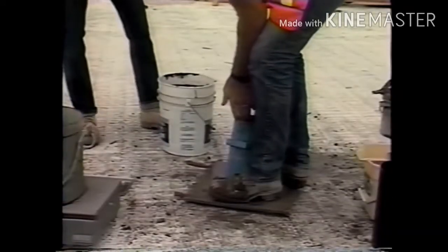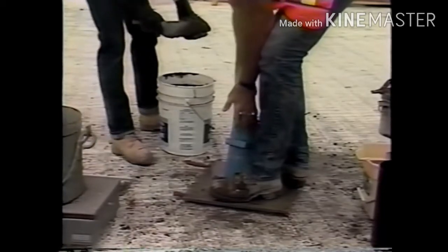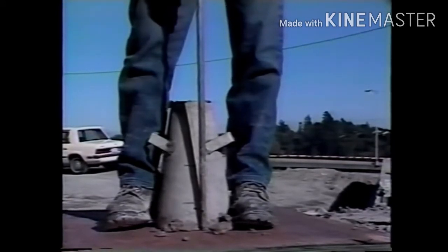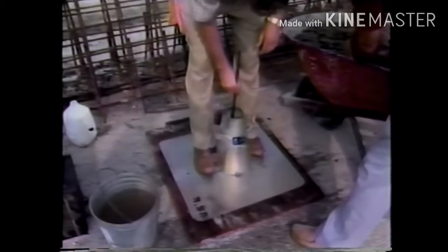As each layer is placed in the cone, it's consolidated with a tamping rod. Starting at the perimeter, with its rounded tip downward, the rod is inclined slightly to match the slope of the cone. Otherwise, the concrete closest to the cone's sides will not be properly consolidated. The rodding should go to the bottom of this first layer, but just tap the base. Each layer is rodded 25 times, with about half of the strokes made near the perimeter.